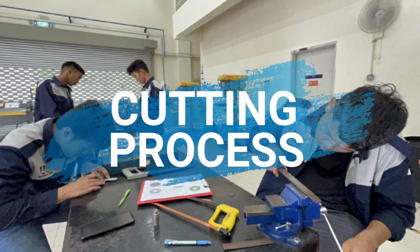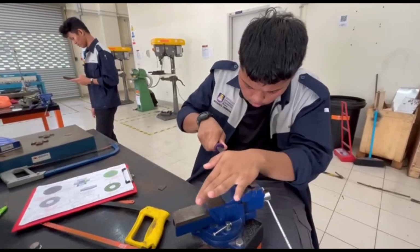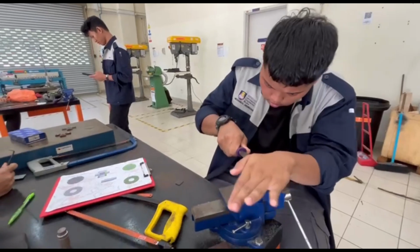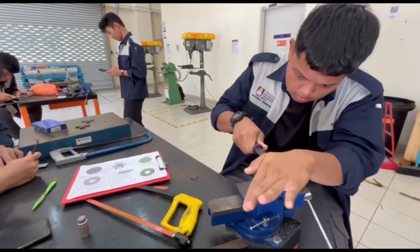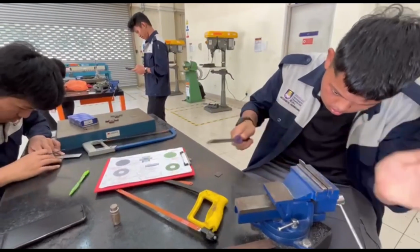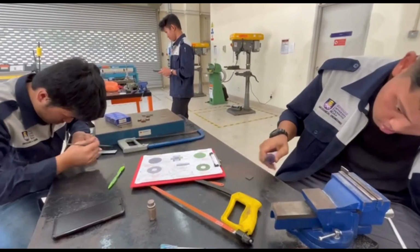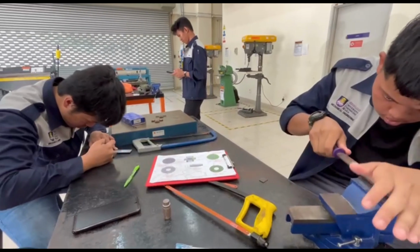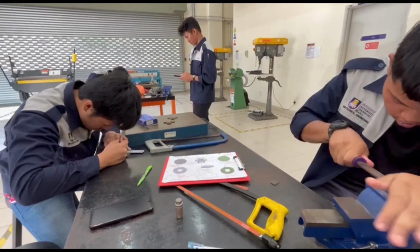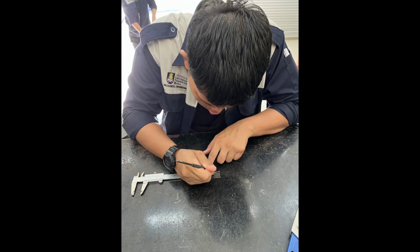The cutting process includes the sawing process. Sawing is a process wherein a narrow slit is cut into a workpiece by a tool consisting of a series of narrowly spaced teeth called a saw blade. Sawing is used to separate work parts into two or more pieces or to cut off an unwanted section of a part. This process is often called a cut-off operation, and since many manufacturing projects require a cut-off operation at some point in the production sequence, sawing is an important manufacturing process.